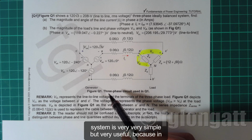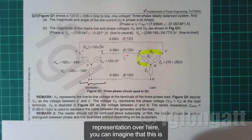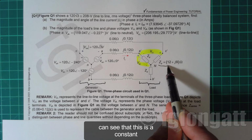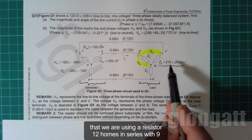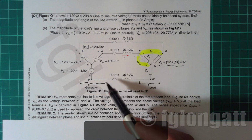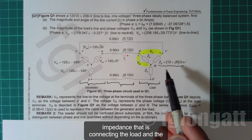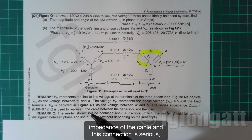So this system is very simple but very useful, because in the future you will understand that this representation over here, you can imagine that this is an ideal AC generator. On the right hand side, you can imagine that this is basically a three-phase load, and you can see that this is a constant impedance load. The reason is that we are using a resistor, 12 ohms, in series with 9 ohms, and that is the inductive reactance. Between the generator and the load, there is a series impedance, which you can imagine as the impedance connecting the load and the generator. This can be, for instance, the series impedance of the cables, and this connection is series, okay?